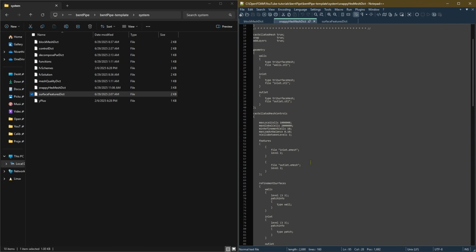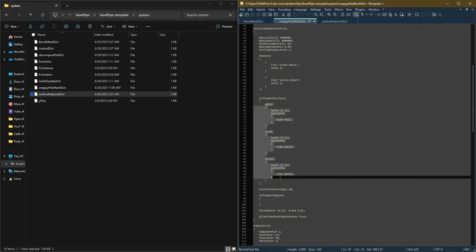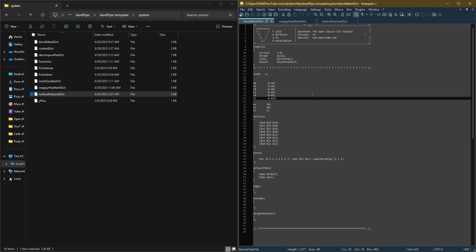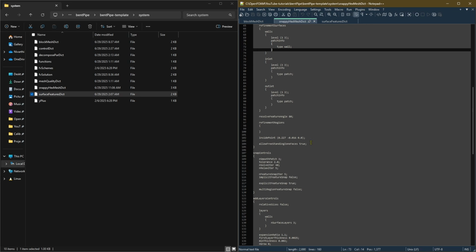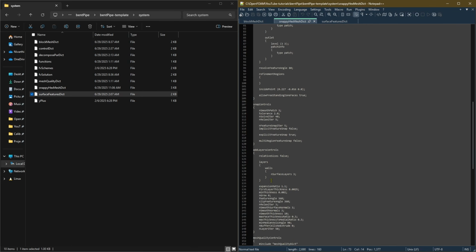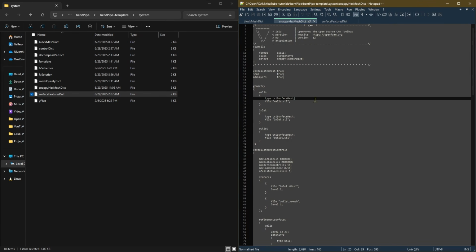But the essential controls that we are trying to use are 2 levels of feature refinement and 3 levels of surface refinement on our base mesh that we have created here. And we'll just go through what this looks like at the end of it all. We're just creating 3 layers here, and this corresponds to what my Y plus should be for the particular turbulence model that we're trying to use as well. So let's get started with the procedure.